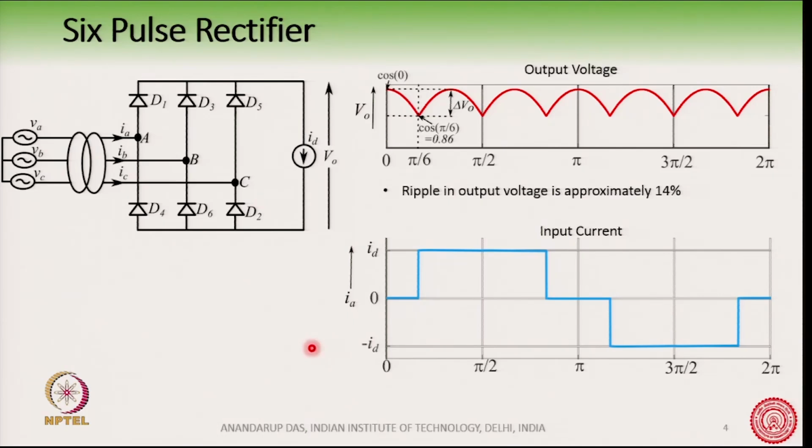And number two is that in case of a fault on the DC side, for example a dead short circuit fault here on the DC side, the leakage inductance of the transformer helps us limit the rate of rise of the short circuit current. So, the transformer leakage impedance should be a certain value.